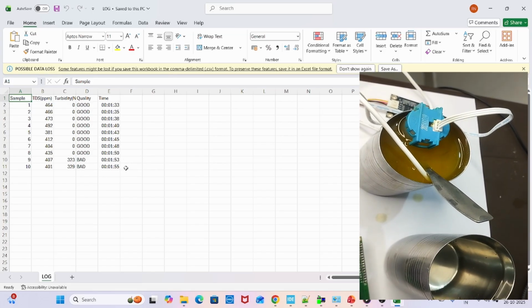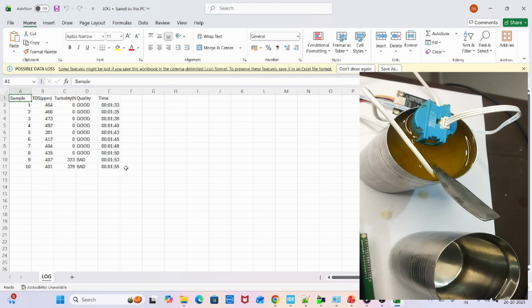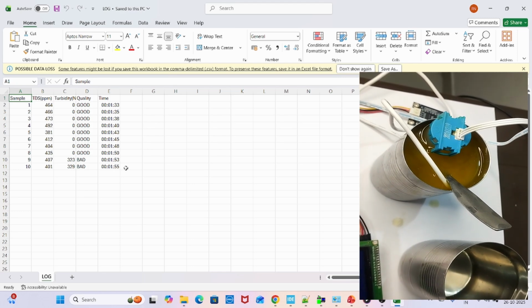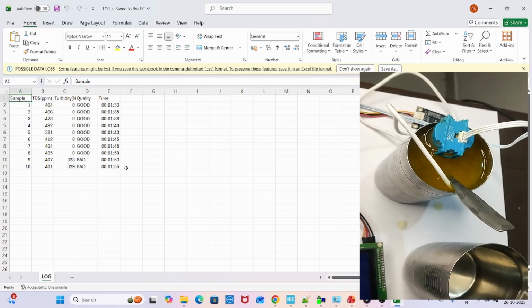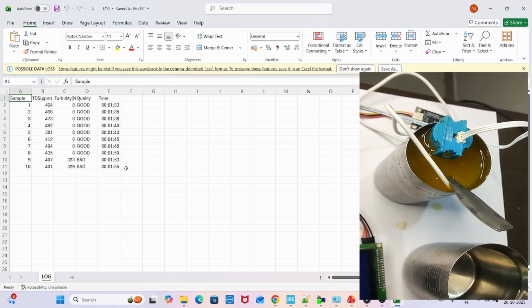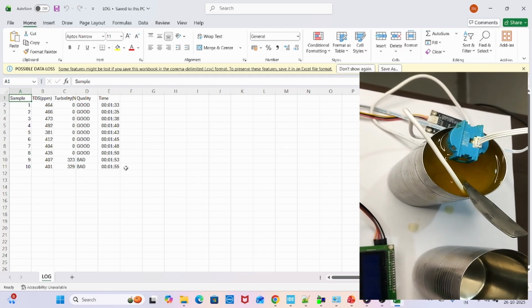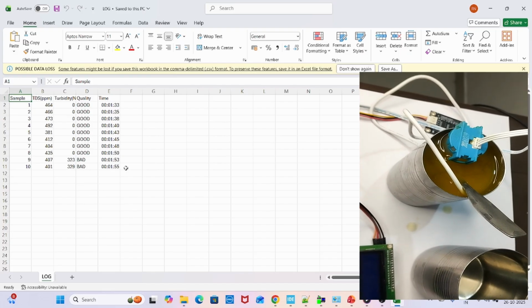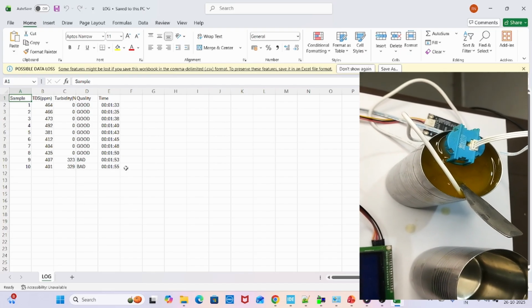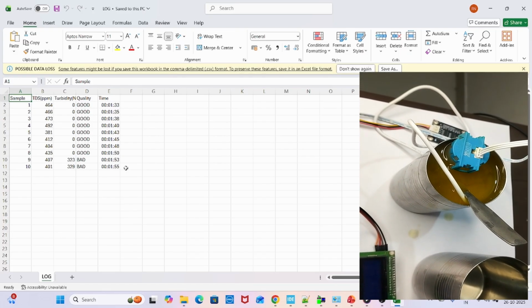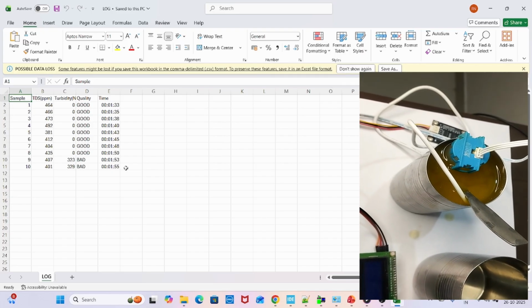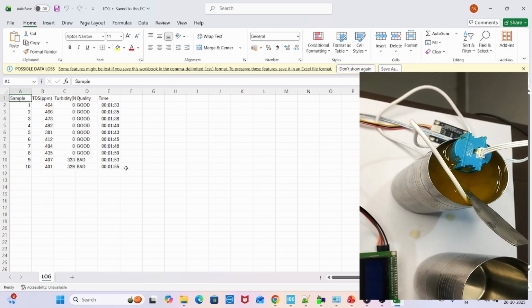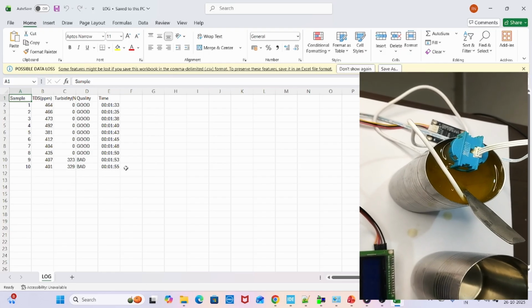So this is simply for 10 readings, but we can also write the code to record the data for the whole day. And at midnight 12, we can simply send this file using IoT over the internet, and then at 12:01 we can format the SD card and again start new logging for the new day. So that is also possible. And in fact, the SD card has a huge capacity, right? 32 GB, 64 GB, so you can log data for months or even for years also, right? So this is what the data logger system is.